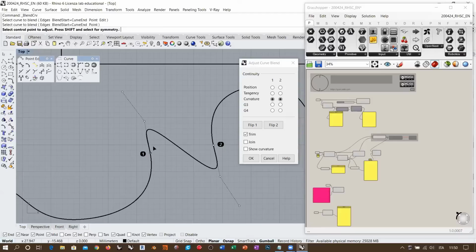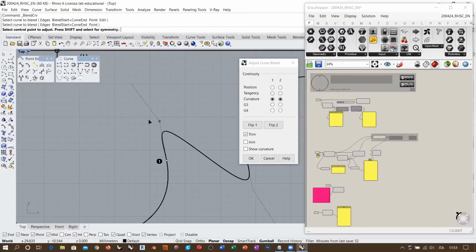If we consider this, imagine doing this by hand, by placing control points directly for a new NURBS curve, okay? Of course, we can place this, eventually we can place this more or less at the correct distance, okay? But there is no way that we can place this by hand, because we don't know what the relation is between these three control points and the radius of curvature of the arc that we would eventually create by placing these three control points. So it's something that is not intuitive at all, okay?